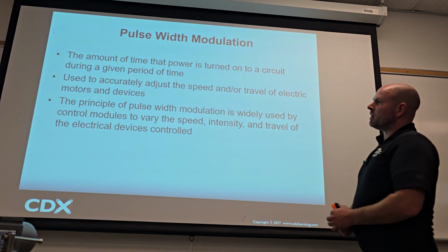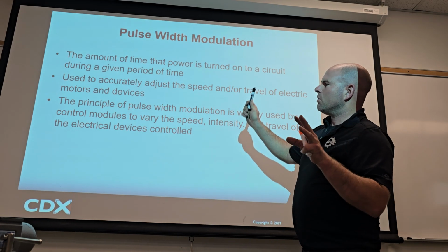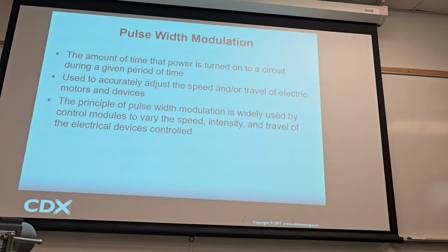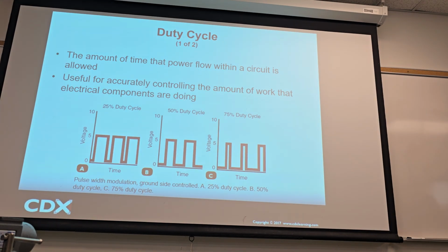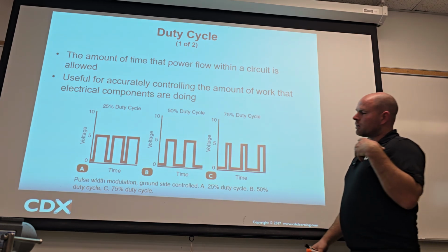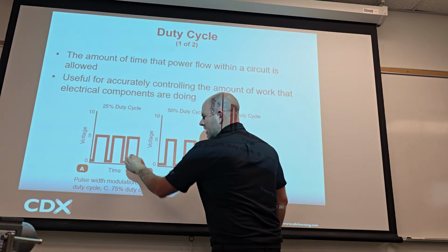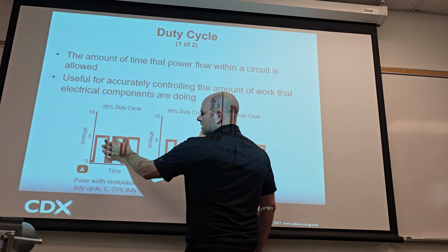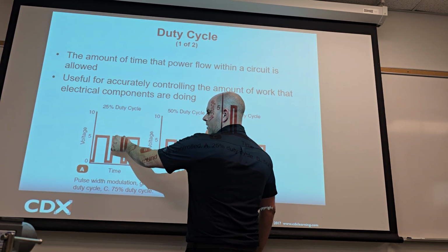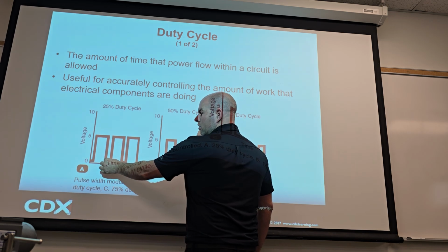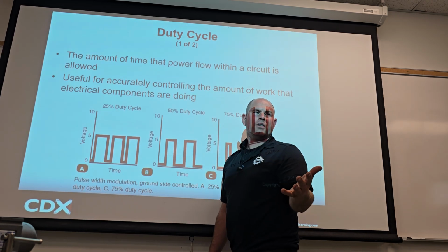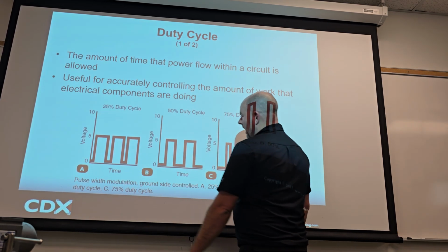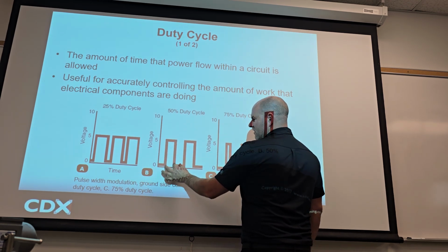And then the pulse width modulation is kind of similar. But remember how we were looking at that picture? That was duty cycle. So duty cycle, I like duty cycle better because it's just a percentage. So if you look at this one, this is about 25%, and this is about 75%. So that'll be like a 25% duty cycle because we're looking at how long it's grounded in this case, by the way. And then right here, it's about 50, 50.